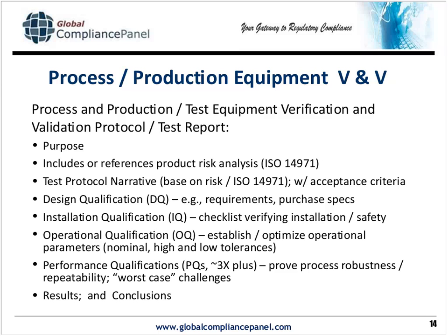So to me, a design qualification most of the time is a requirements spec. The installation qualification to me is a checklist to verify all the things required to make sure that that piece of equipment or process has been properly installed. Let's say it's an injection molding piece of equipment.